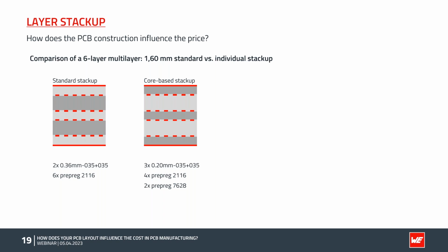What's the problem here? Well, when we do the structuring of this core, we normally structure top and bottom side in parallel when you go to the inner layer manufacturing, like you would see on the left side. For plating, we need to have a fully covering copper on the outer layers after the lamination.